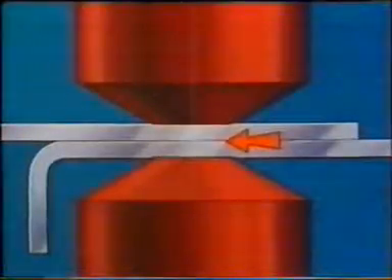2 thin sheets of mild steel are placed between the electrodes and pressure applied. The welding current is switched on and it flows easily through one copper electrode into the first steel sheet. But here it meets high resistance because steel is a poor conductor of current and heat, and there is a junction between the sheets.